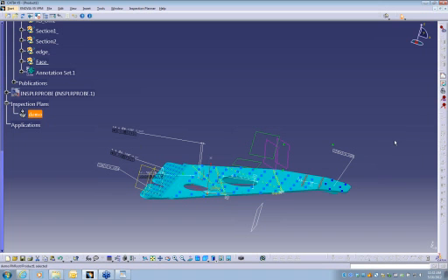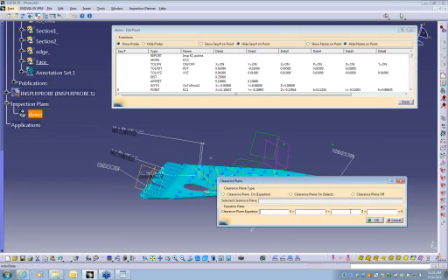The thing is, if we wanted to, just like in CATIA NC, we could have turned on a clearance plane. So let's say we had a bulkhead part with pockets in. We could have set a plane to maybe Z 1 inch, and then we would have never had to worry about leaving one pocket going into the other pocket. So we have pocket type information or clearance plane information.